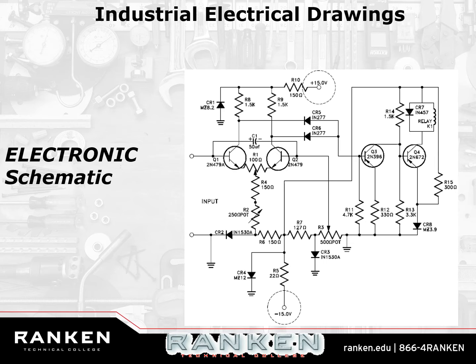So shut it down if you can. Pop open the main cabinet, or wherever you're looking at. Or more likely, you're going to go into the diagnostic screen on the HMI. It's going to tell you what isn't running, and you're going to be able to go into the ladder. You're going to look at the ladder, and you're going to say, well, the main isn't coming on. One of these outputs isn't going to true. None of these outputs are. Well, that's kind of strange. All the outputs can't be off at one time. That's kind of nuts.